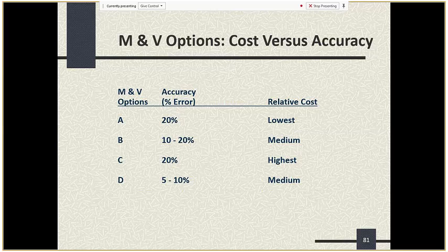It's not in your slide, but in all the federal projects that are done by the federal government, which is billions of EPC projects, 61% of all the projects use option A, by far and away the most common method of M&V. Option B is used 17% of the time. Option D, the simulation type, is used 14% of the time, and option C is only used 8% of the time. Well, there's a reason for that.